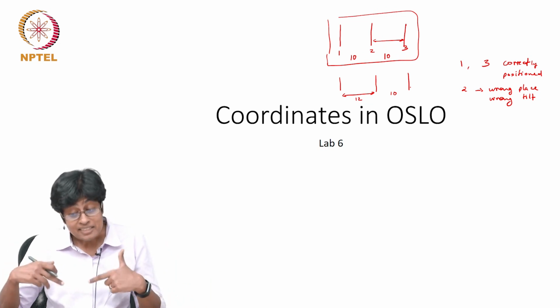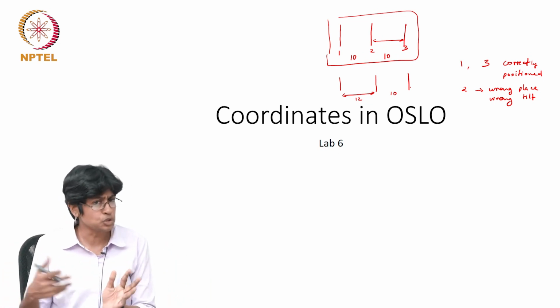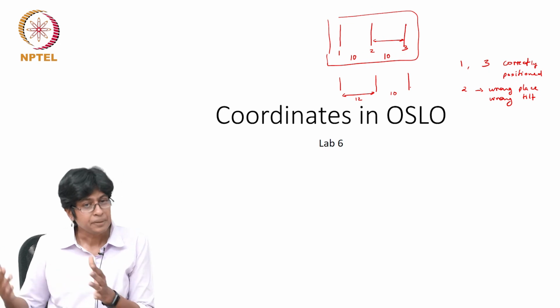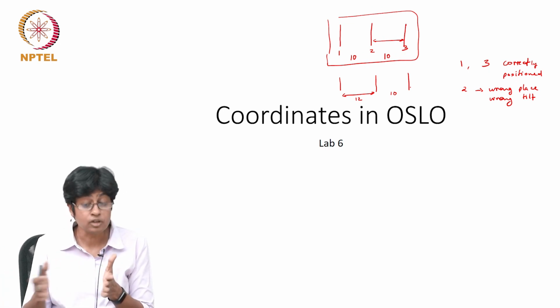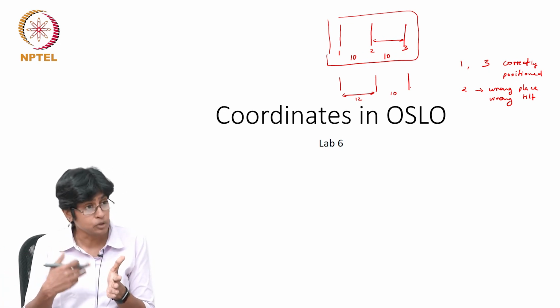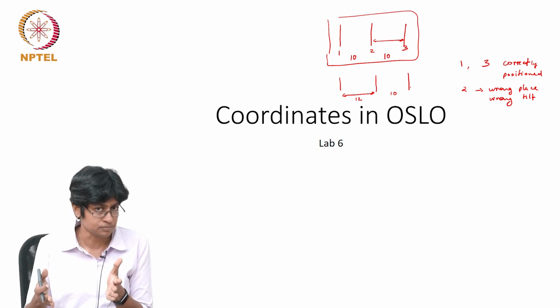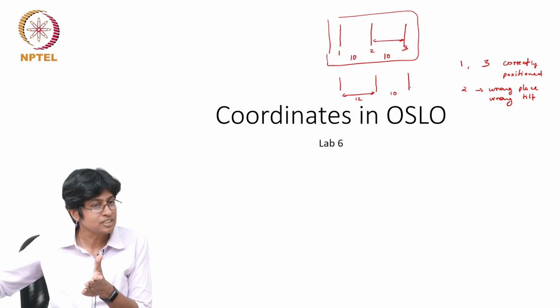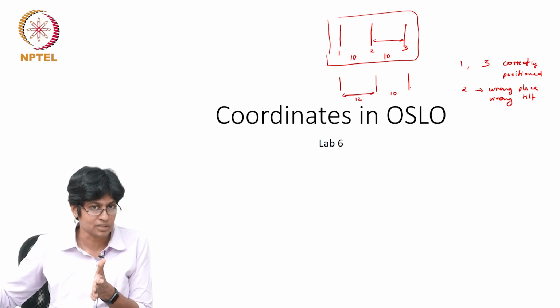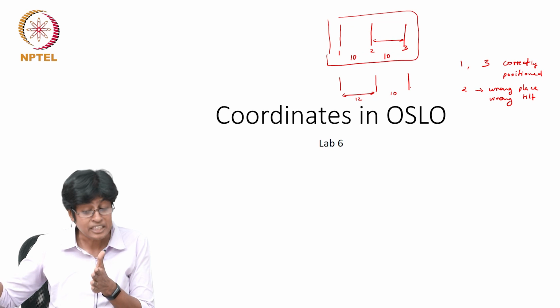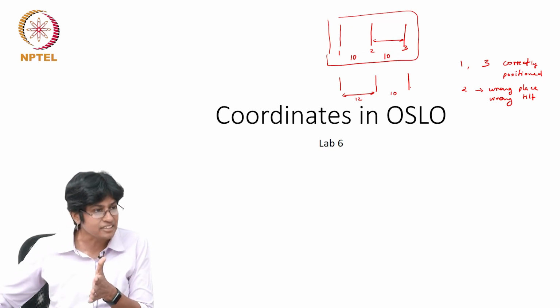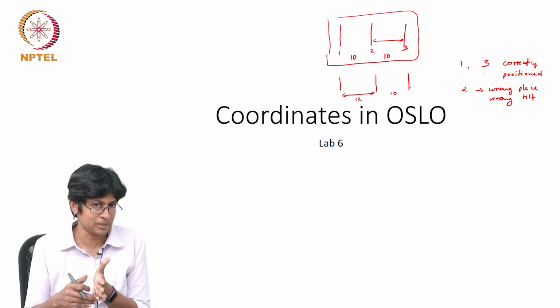So in this case, you might say, well, I know it's 2, I'll adjust the next distance. But sometimes you want to study the effect of varying. So you may do a study where you say, let me vary the position of element 2. And I want element 3 to stay in the same place during this study. I don't want element 3 linked to the coordinate system of element 2.